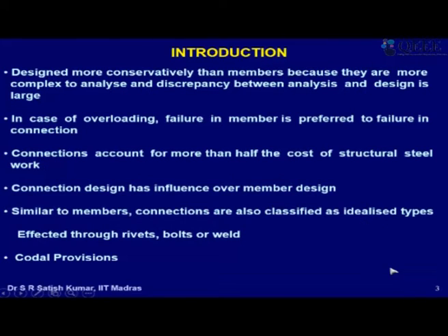You just attach it so that it can transfer only the shear force. And we also neglect, as we saw in compression members, the line of action from the face of the column to the center line. We actually transfer the load at the face of the column, but we assume the column as axially loaded. So we do make some simplifying assumptions so that our design can be completed quickly, but then we should make sure that they are valid to a large extent.